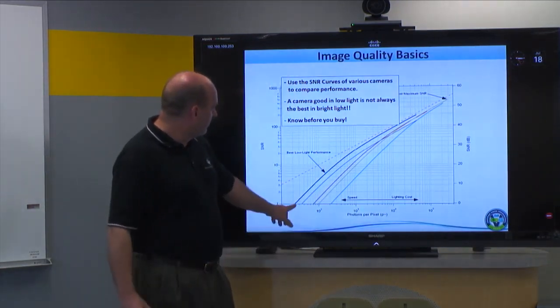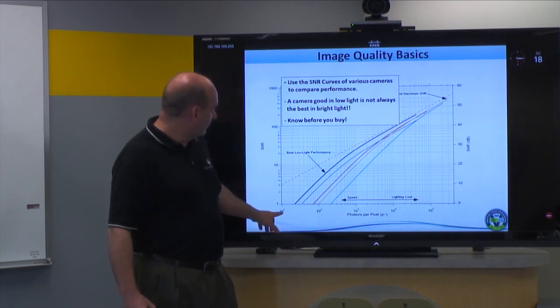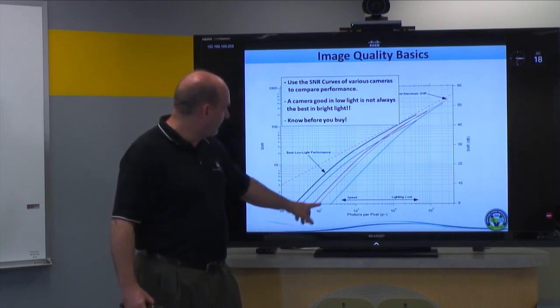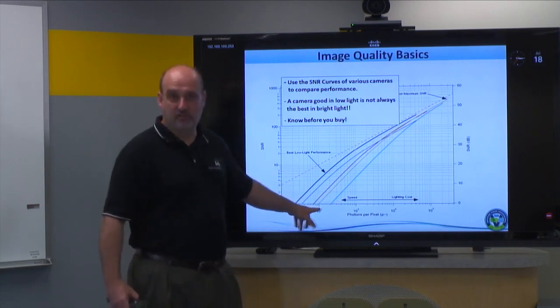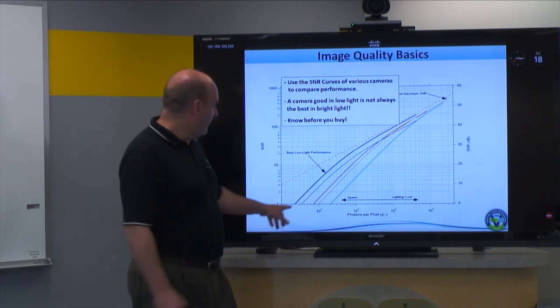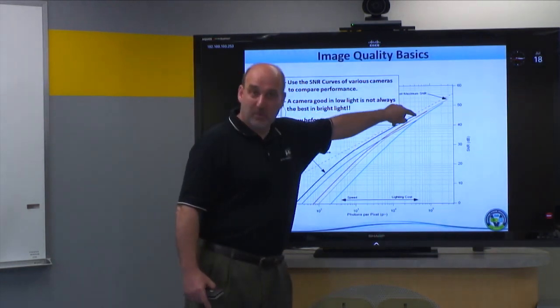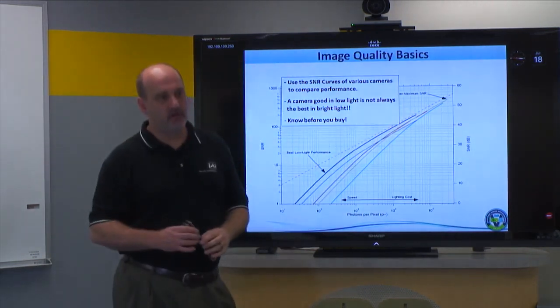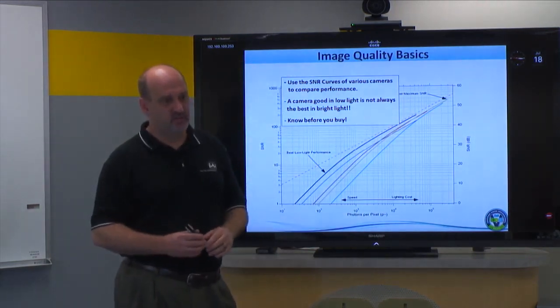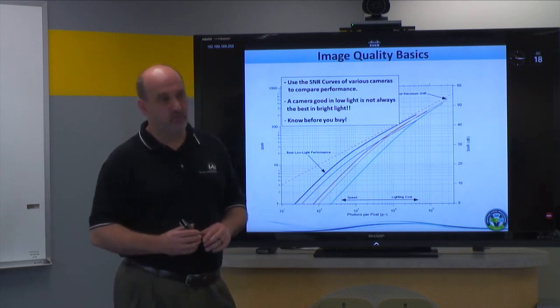So again, you can tell each of these cameras has a different point where it drives into the light. This is coming down to 1 lux, this is 100 lux. The cameras with the highest dynamic range are usually the ones with the poorest sensitivity, because if I have good sensitivity and high gain, that means unless I have a really big well, my well saturates faster. So typically these things are a little bit at odds with each other, and you want to pay attention to the cameras, where the data is available, and where you're going to use them.